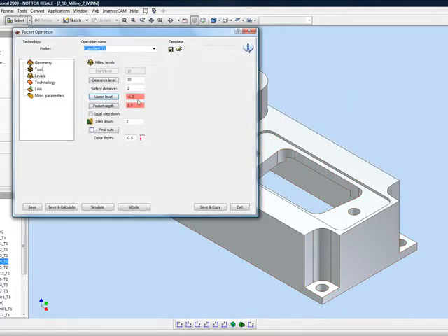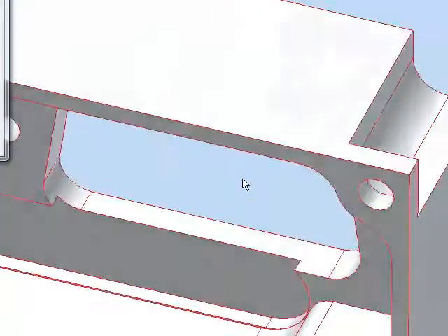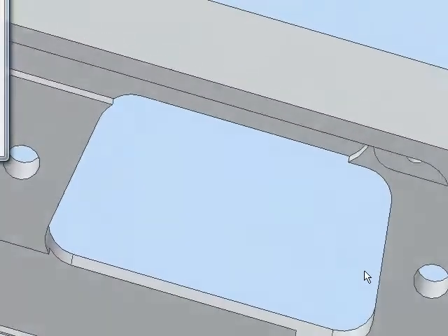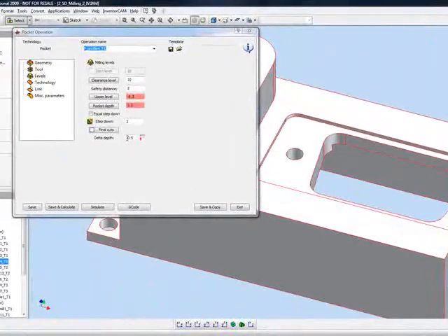And my lower level is actually the very bottom of that particular pocket, up until this point over here. However, I've also given it a delta depth of a 0.5 millimeter to go a little further down past that point itself.